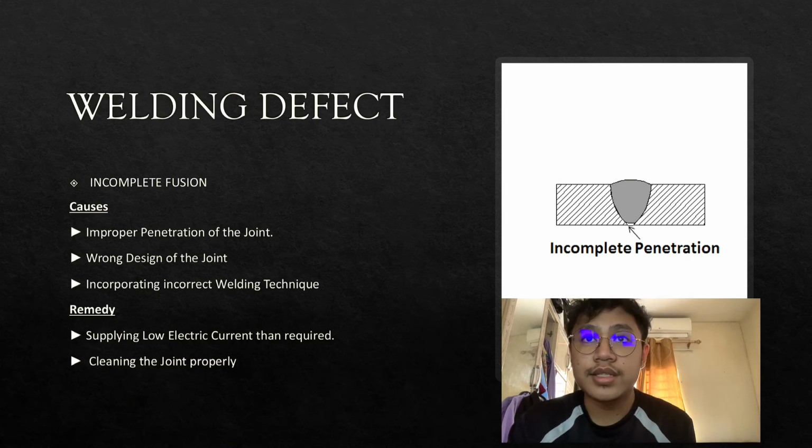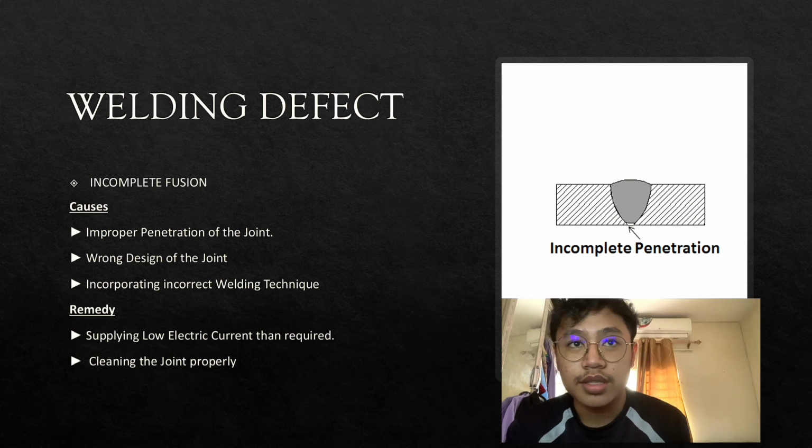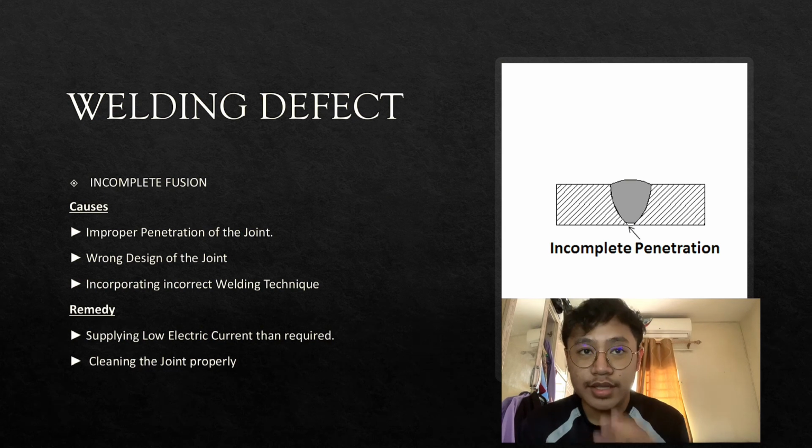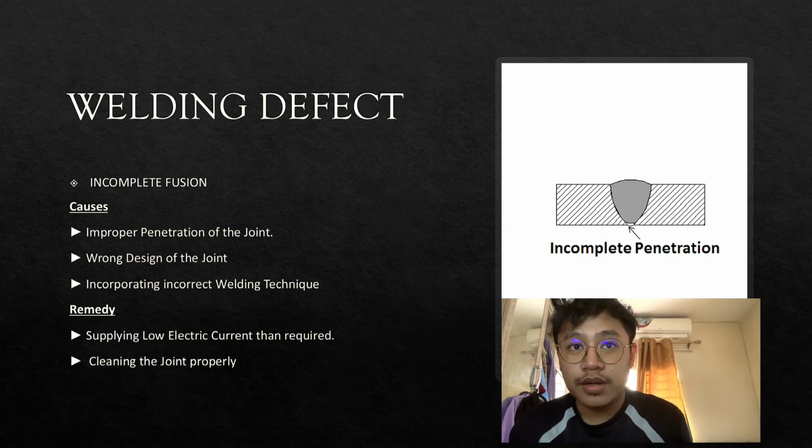Next, incomplete fusion. The cause is improper penetration of the joint, wrong design of the joint, and incorrect welding technique. The remedy is supplying the required low electric current and cleaning the joint properly.